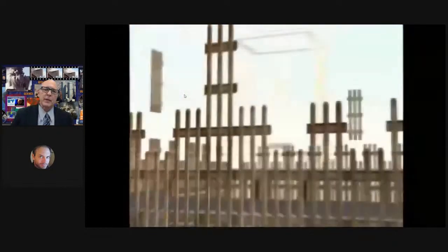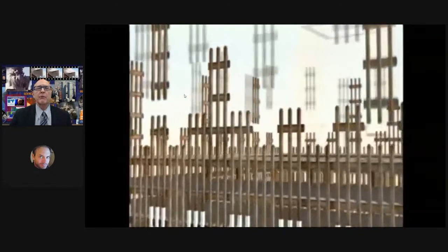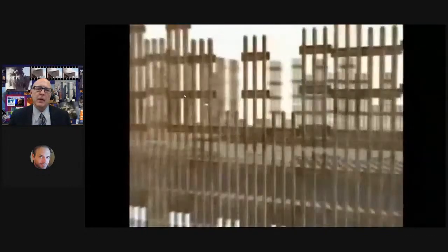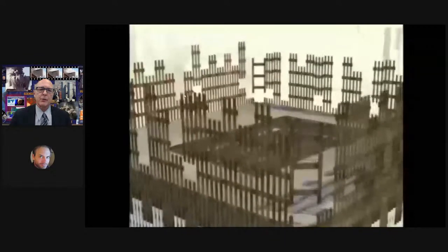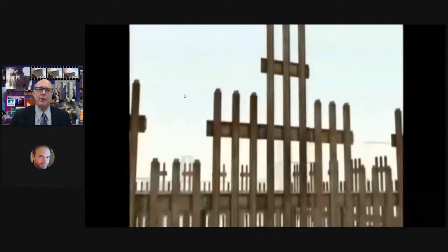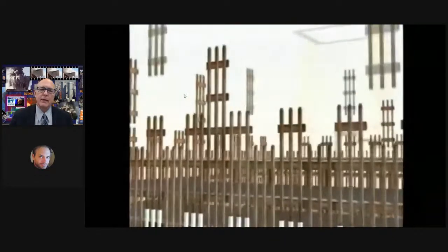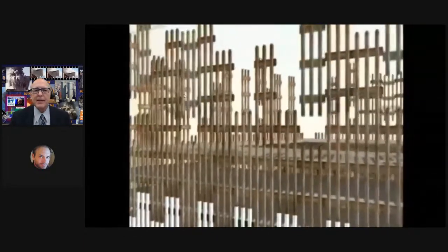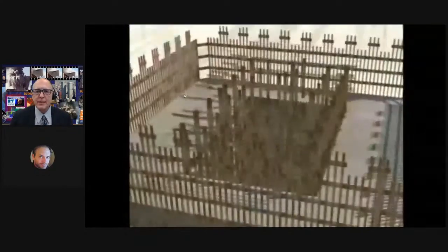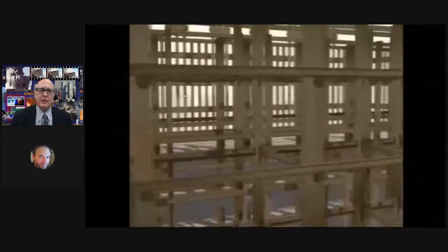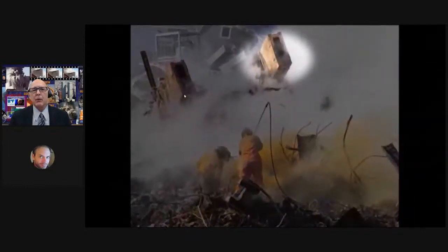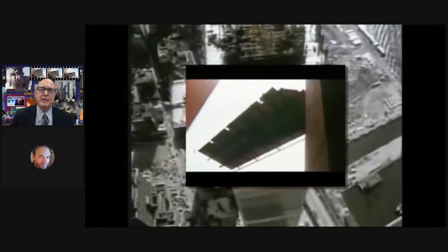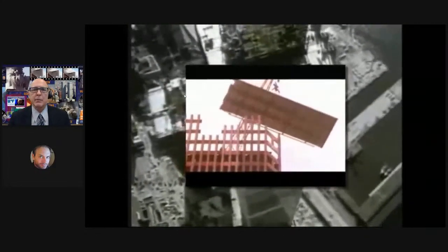What they did with the Twin Towers, though, was move back half the columns to the perimeter in an exoskeleton with 3 vertical welded to 3 horizontal structural members, which were brought and erected in place with cranes and bolted together. Inside, we had a massive series of 47 incredibly dense core columns, which halfway through the structure at mid-height, they're 22 by 16 inches, and then solid steel at the base.